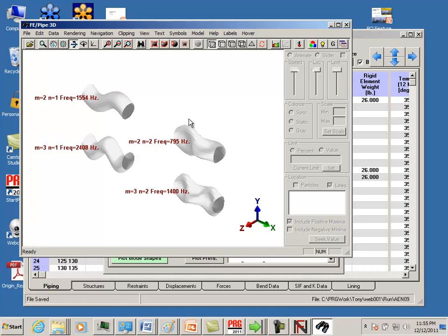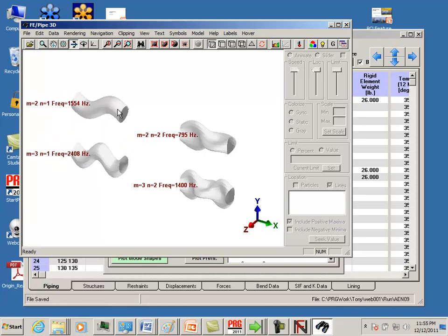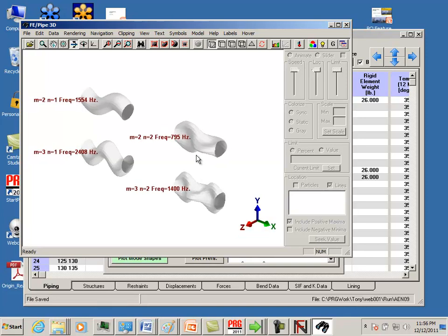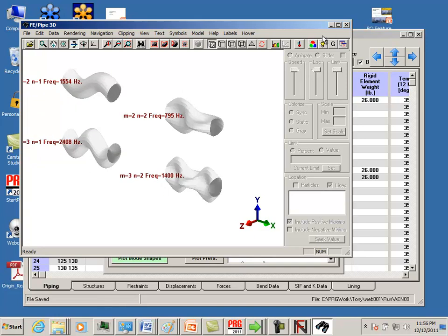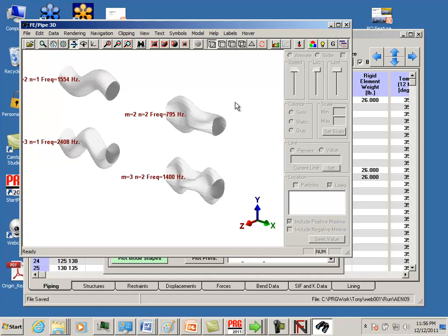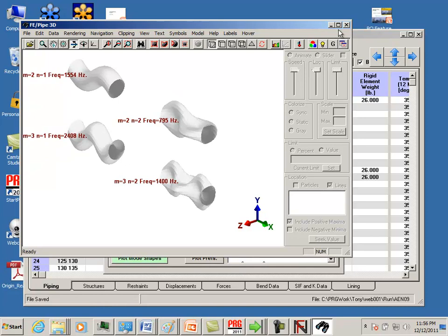Here though, these are the beam bending modes. Plane sections remain plane. Here are the acoustic induced vibration or shell bending modes. So these are the modes that you'll calculate in a 6 degree of freedom pipe stress program like Caesar. Here are natural frequencies that you can calculate in an 18 degree of freedom pipe stress program like the PCL. Fortunately, they're orthogonal and don't interfere with these mode shapes much. But this is a part of what needs to be done when acoustic induced vibration is evaluated.